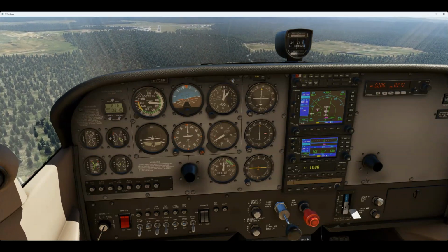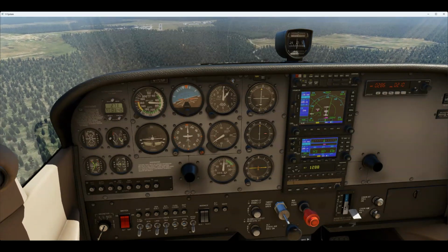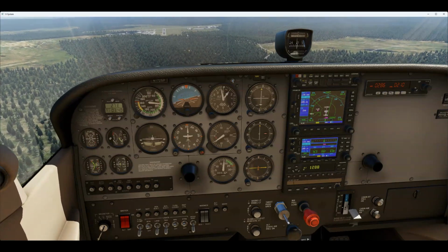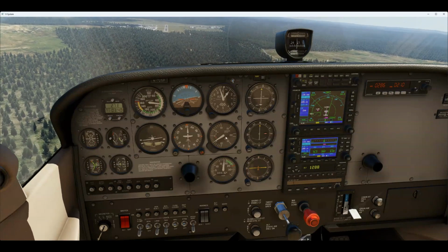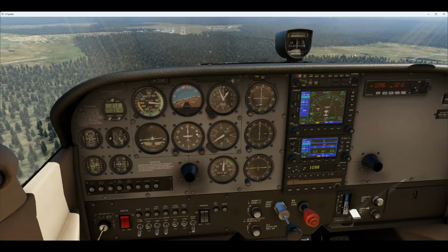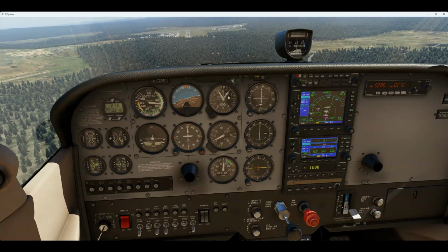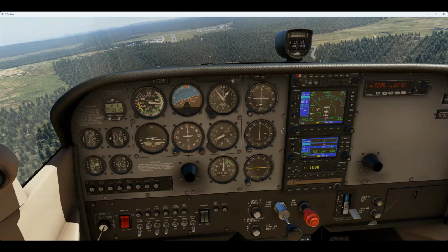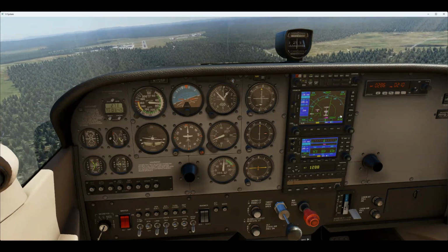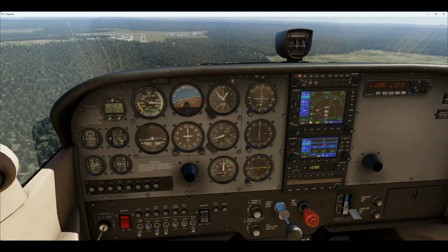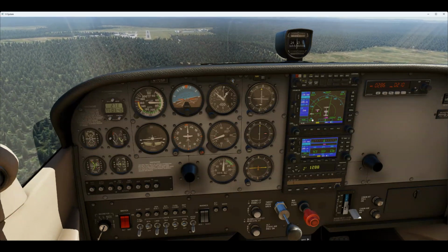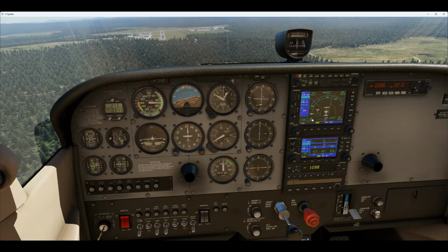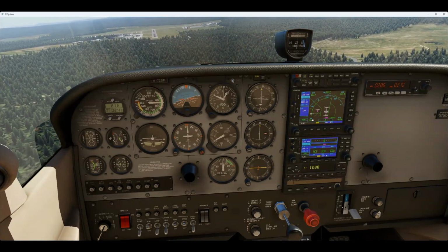All right, keep on coming down. And we're coming down. So we keep looking CDI, GPS, vertical speed, and heading bug. CDI, altitude, CDI, that, then that. And when I'm on this, I look at the track and I look at the ground speed. I kind of match the two up. So it's telling me I want to fly down a bit more, reducing power a little bit, telling me to fly right a little bit.